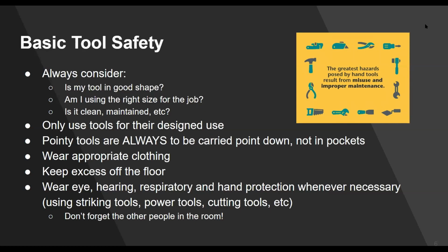Pointy tools always carry down. That's not just in shop, but at the competition as well. Always know where the points are, and as much as possible, not towards other people. Wear appropriate clothing. That's just a big one. Seems like a no-brainer, but if you're working with heavy things, make sure that your toes have either steel caps or just sturdy boots so that nothing is going to pierce through them or crush your toes.